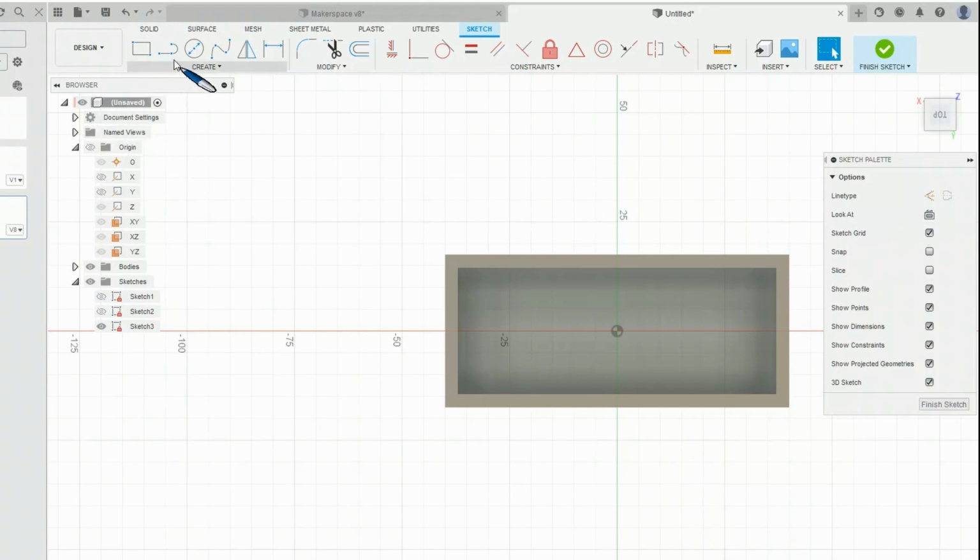So first thing I'll do here is go for this particular tool, which is the line tool. If I also just press L, it'll bring this one up. Now if I just drew a line by clicking 2 points and hit escape, I'll get a solid line. For the purpose of what I'm doing, I actually want a construction line. Now I can change that to construction by selecting it and clicking on this here, and it'll become dotted, or just delete it and start again. I go line tool, line type is now construction, and any line I do from this point forward until I change will now be a construction line.